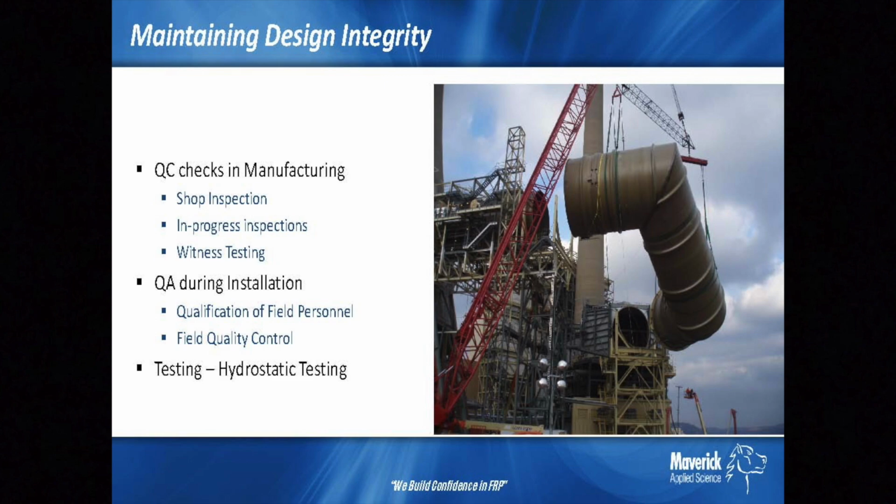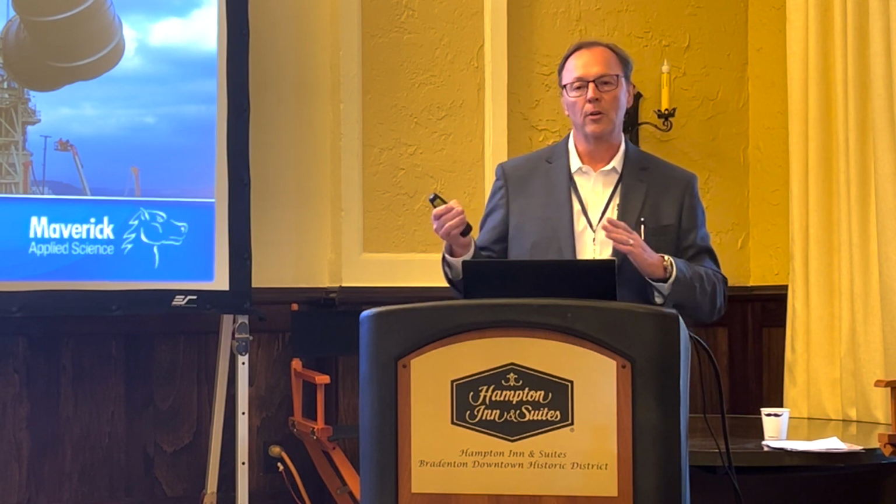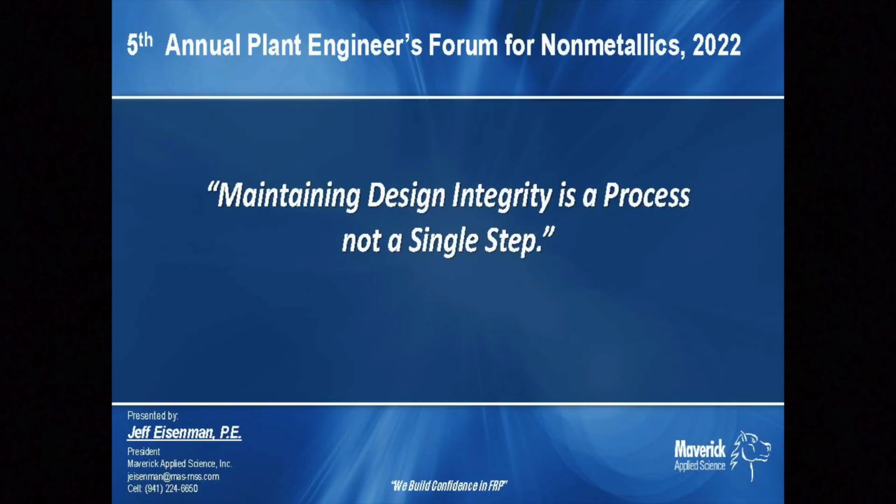We talked about qualified vendors, particularly with piping. RTP-1 specifies that a certain number of qualified fabricators have to be involved with the project. With piping, pretty much every laminator needs to be qualified. So you should be expecting that. That should be a point in your specifications if you have specifications for your equipment. And with piping more than tanks, you want to have that field QC element, because there's a lot going on site as well.